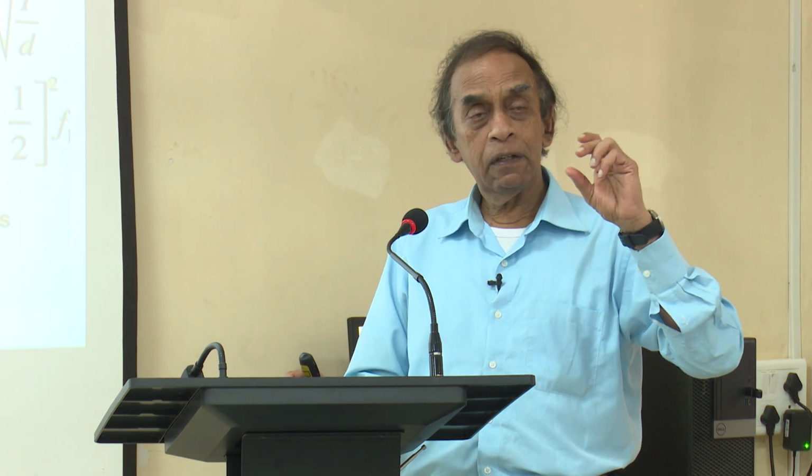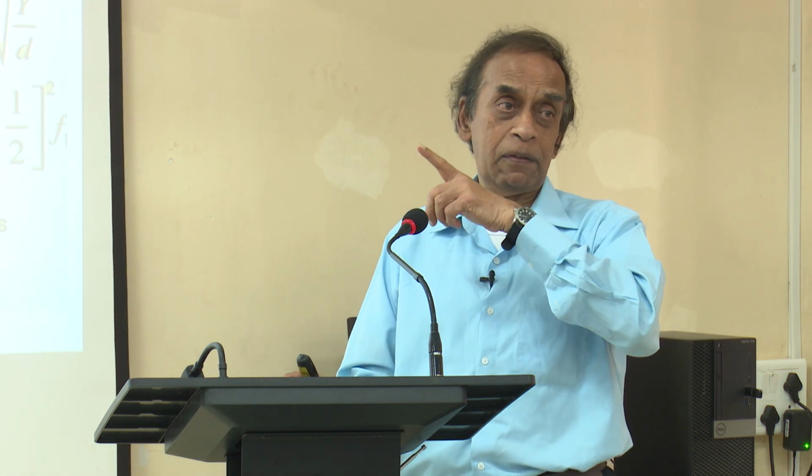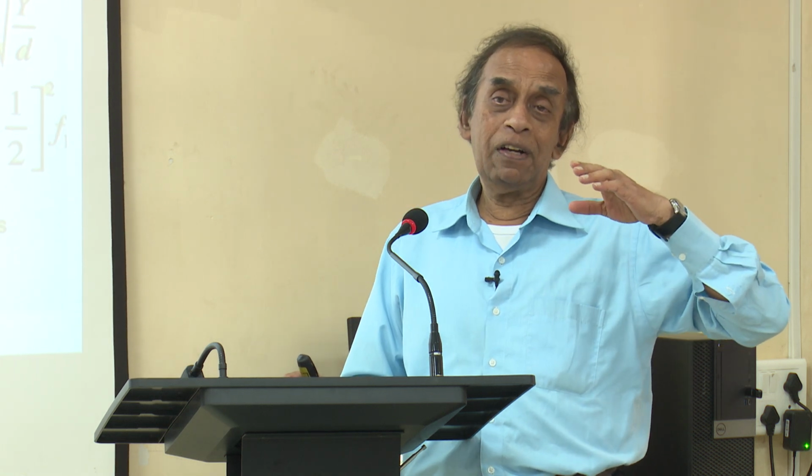The other alternative would be you can take a bilayer and measure the capacitance versus frequency. Wherever the resonances are, you will see a spike in the capacitance or the dielectric constant. So whenever we do the experiment, we first run the capacitance measurement, identify where the resonances are.